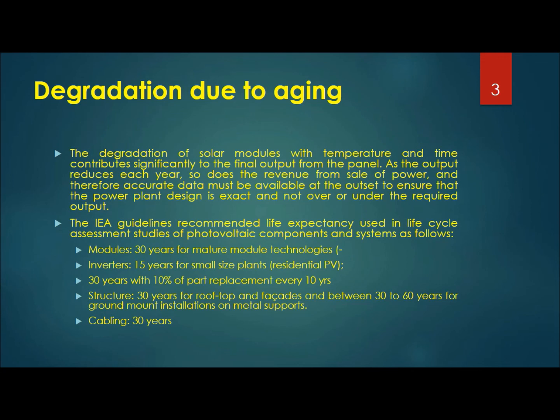These tests have successfully demonstrated that there is module degradation, and the possible reasons for this are the slow breakdown of a module's encapsulant and back sheet, the gradual obscuration of the EVA layer, that is ethylene vinyl acetate, between the module's front glass and the cells themselves, and the deterioration of solar cells due to temperature increase.